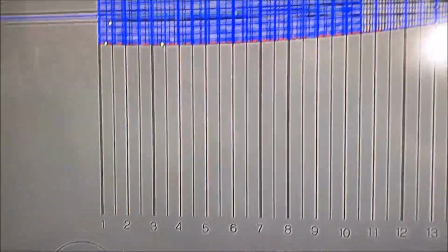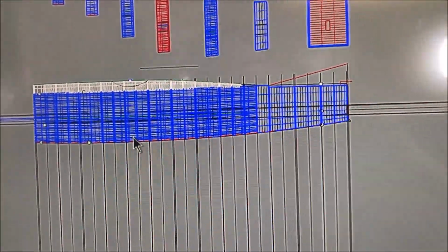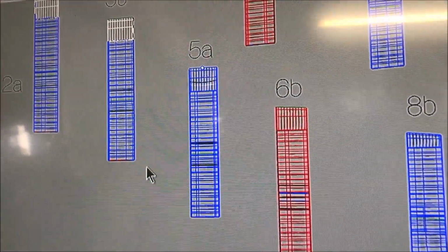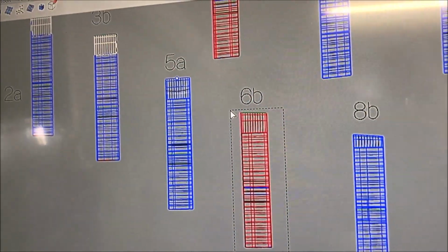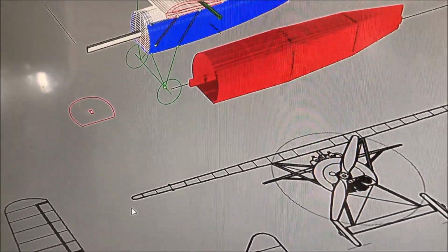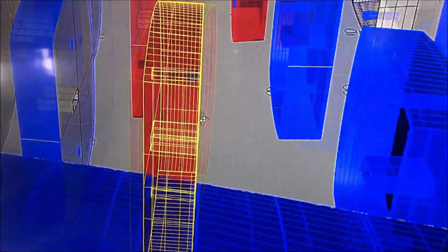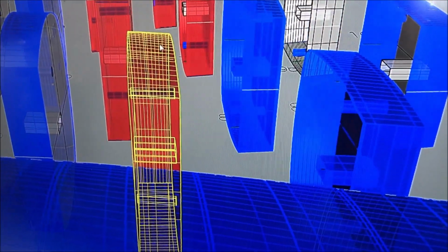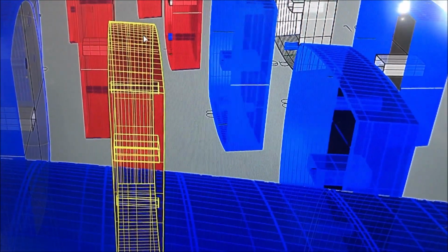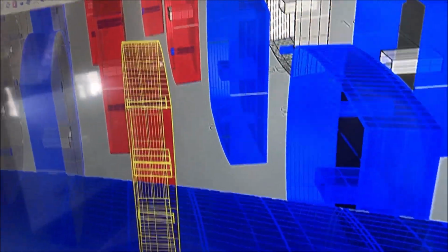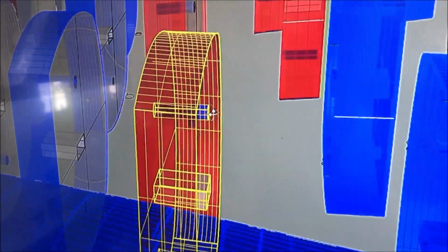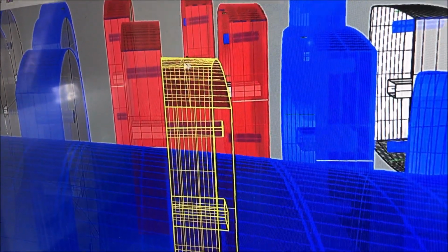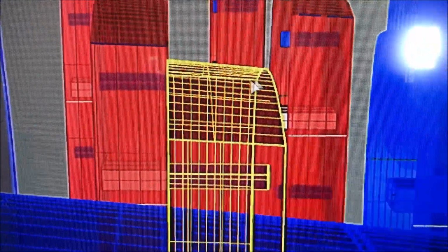The foam shapes, because this thing tapers so much, like most fuselages, they look sort of square there, but if you highlight one of these and then go look at it in 3 view, it's got taper to it. So you could just slice it up, stick a bit of foam in, it's like a foam blank in there, and sand the foam to shape. But I hate sanding foam. So we take this and get the machine to cut it to this taper. We get the router to cut it to this shape.